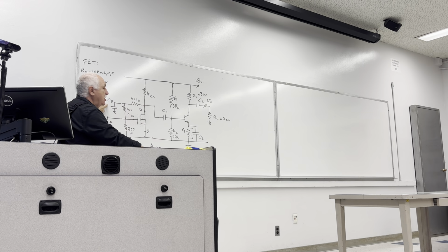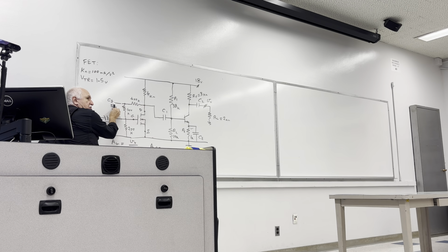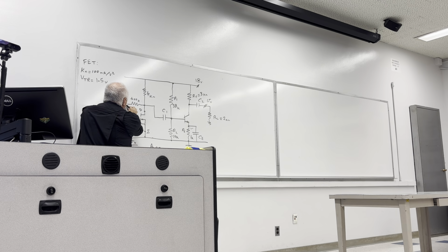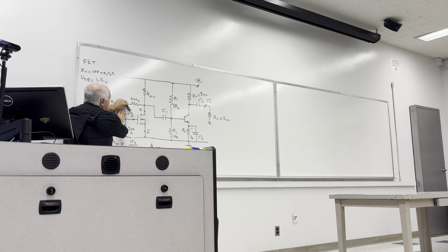This is the answer. If you put a large capacitor here, large enough, this capacitor will be a short circuit. Once it short circuits, it will short that point to the ground. So when you're applying an input signal here and the output changes, the signal will not return back to this input, because it will be shorted straight to the ground.